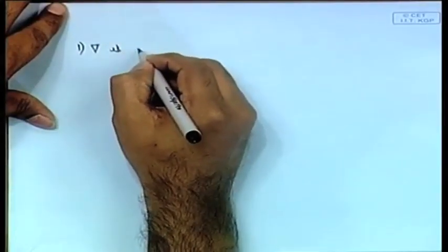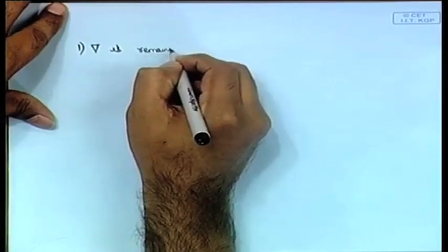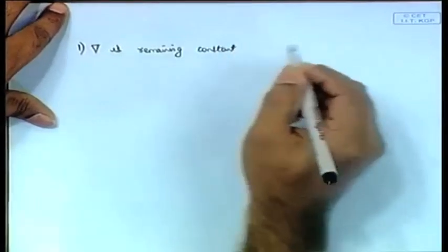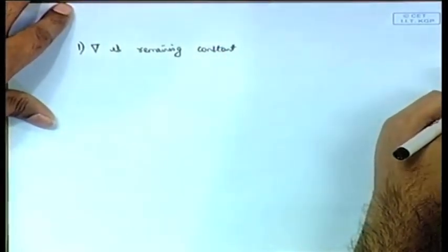Okay. So, last class we mentioned the motion of the metacenter. We called it the M curve, how the metacenter moves along with the heeling. Now, note that in general we assume one thing in case of all this heeling, that is, we assume that the displacement delta is always remaining constant. This is an assumption that we make in the development of all our mathematical theories.